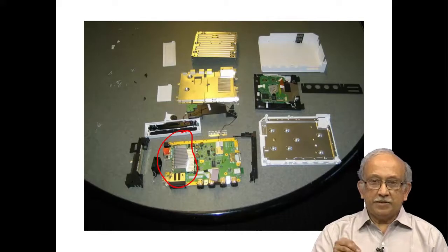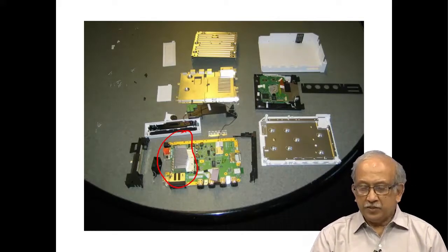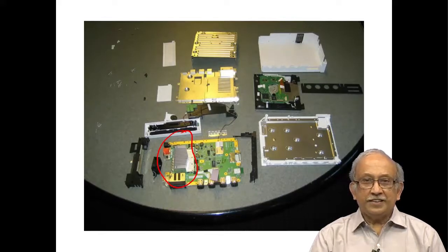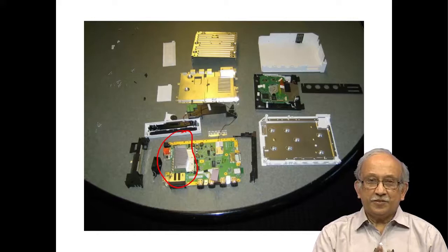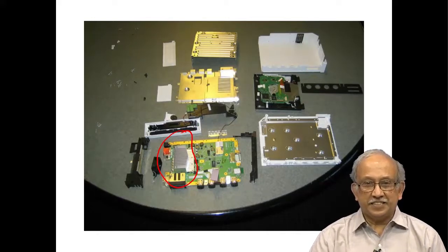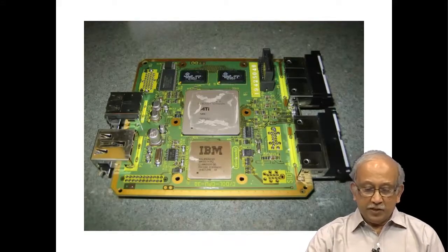That is, they take it and dip it in this. So, it will prevent another level of corrosion and so on. And something which is very important is that it will make all the finishes compatible. They look good, and there is no electromotive potential between the finishes which will cause degradation of this. So, the next slide shows a little closer